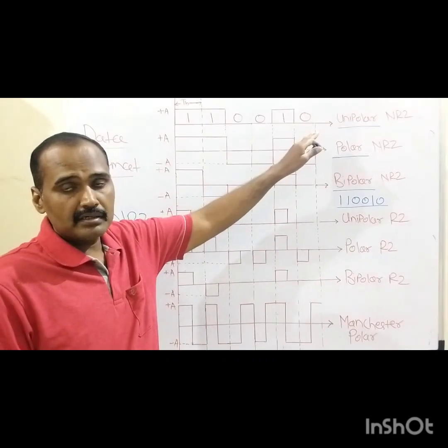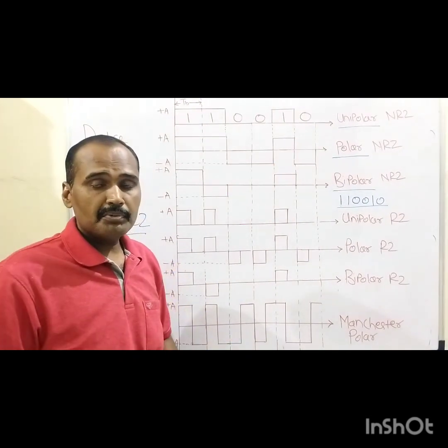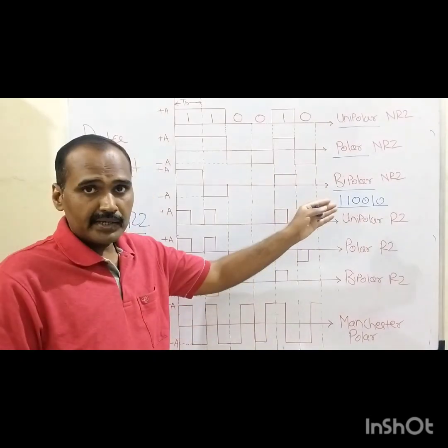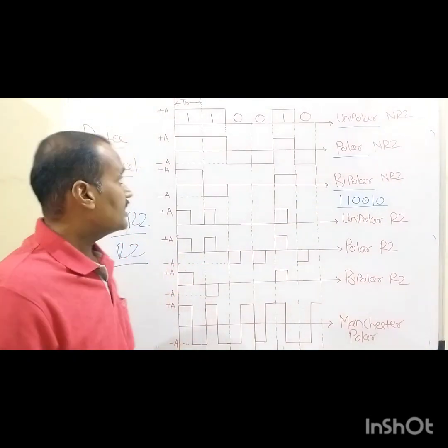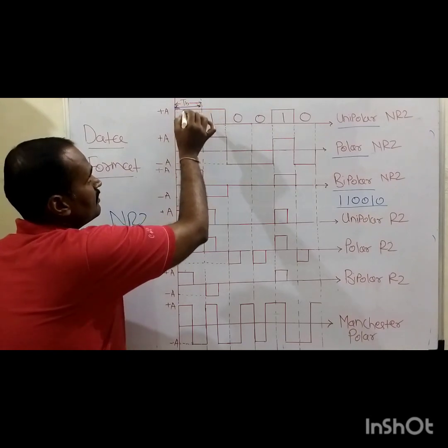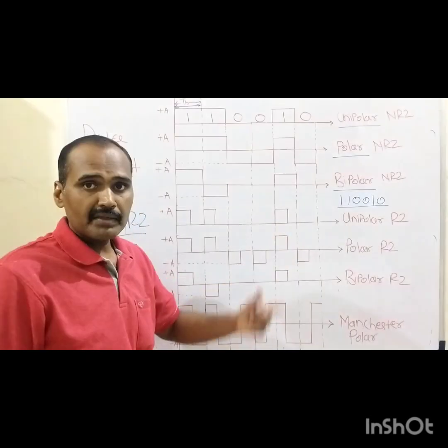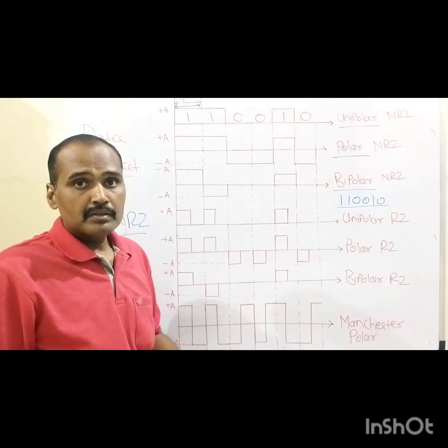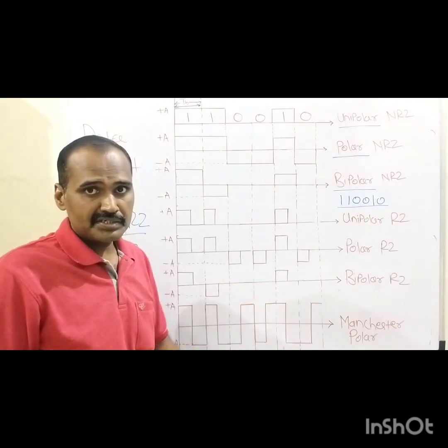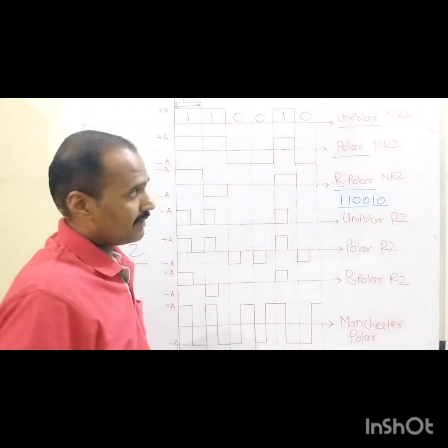This is how these binary bits are represented, where we have a particular bit duration which is uniformly defined for each and every binary bit. That bit duration is denoted by the abbreviation TB, which stands for the bit duration of each 1 and each 0 in this symbol sequence. So the first type of digital format used in digital communication is the unipolar NRZ type of sequence.